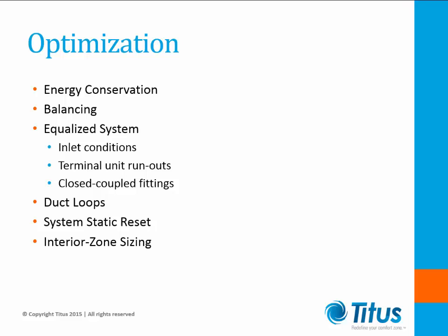Eliminate close coupled fittings. Fittings in line will have a multiplying factor of their friction loss and should always be avoided.